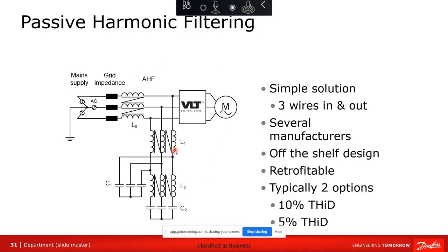Several manufacturers, quite upfront, I use MTE matrix filters. There's Transcoil TCI is one that I know of. I actually make my own. The company probably wouldn't be happy with me saying this, but I make my own. I make them in Germany, and they're typically longer lead times. And I do not include a capacitor disconnect in mine. The MTE matrix filter does include the capacitor disconnect here. So that's a big benefit.